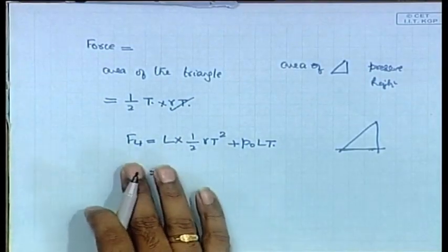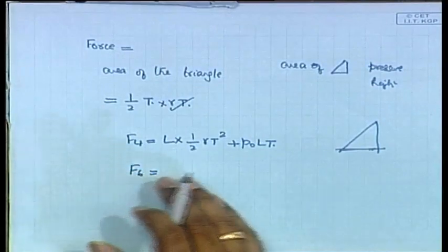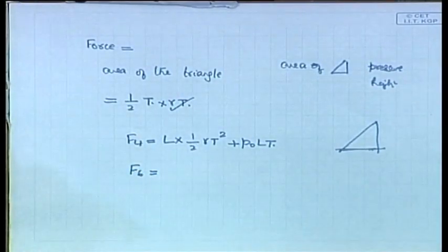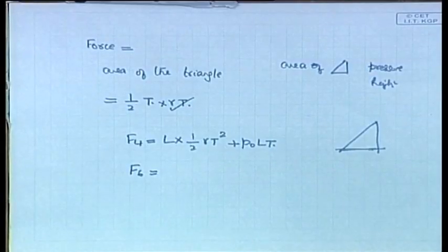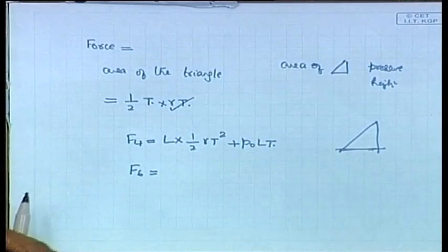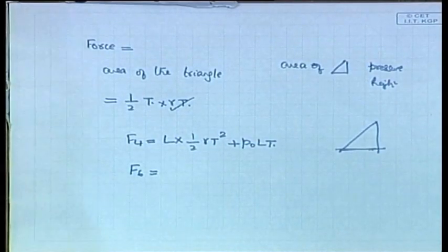Again, just remember one of these derivations, means just remember the first one. All you need to do is integrate the pressure over that depth, you get the force. So, you get F4, and in the other case you get F6 in the opposite direction as F4.